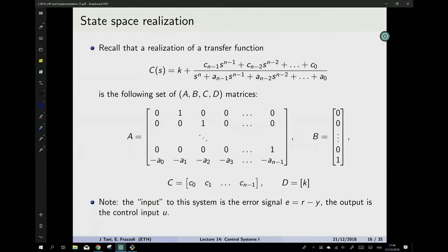It's called the canonical observable, no, this is a canonical controllable form, well, whatever. This is a good realization, okay? What does it mean? It means that if you use this A, B, C, and D and calculate the transfer function with the known equation, you get that thing up there. Quick look, how do you remember this?